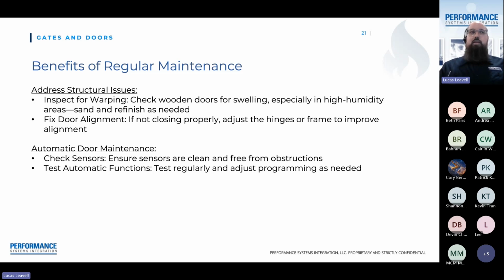They're probably, mechanically speaking, the number one thing that needs to be replaced when it comes to access control and security doors. After that, anything involving an automatic door needs to have its sensors periodically checked, calibrated, and oftentimes they may need to be replaced. This is especially true if the sensor has a plastic cover on it. Plastic can scratch. Plastic can get covered in debris. Some people even paint over them, not knowing what they are. Well, that will prevent the sensor from working correctly.